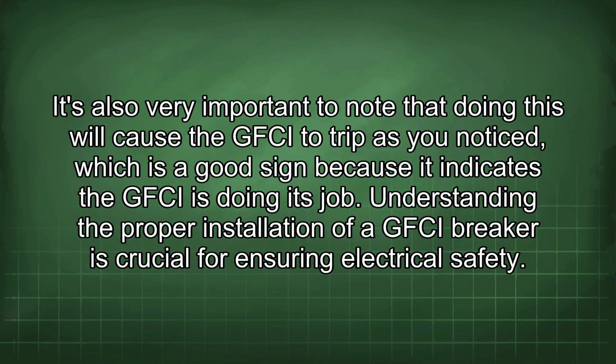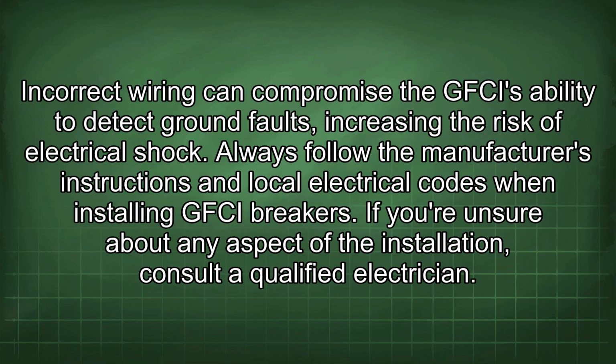It's also very important to note that doing this will cause the GFCI to trip, as you noticed, which is a good sign because it indicates the GFCI is doing its job. Understanding the proper installation of a GFCI breaker is crucial for ensuring electrical safety. Incorrect wiring can compromise the GFCI's ability to detect ground faults, increasing the risk of electrical shock. Always follow the manufacturer's instructions and local electrical codes when installing GFCI breakers. If you're unsure about any aspect of the installation, consult a qualified electrician.